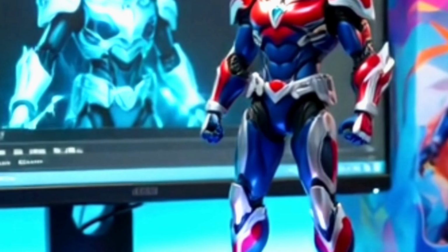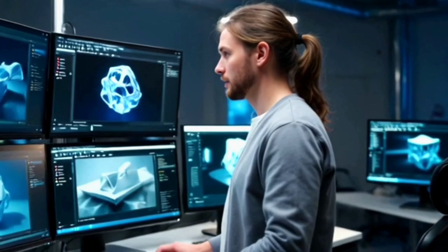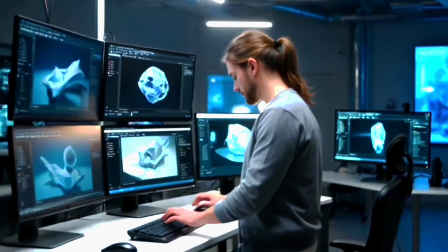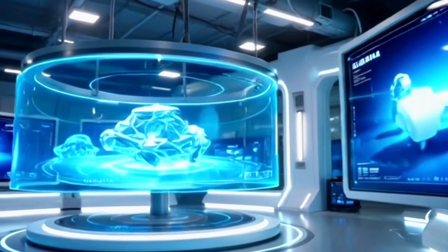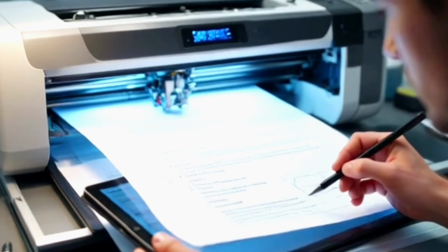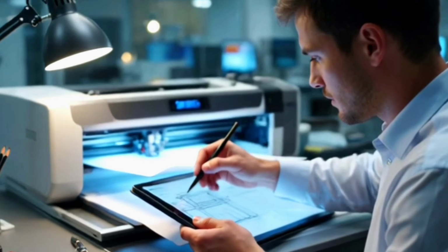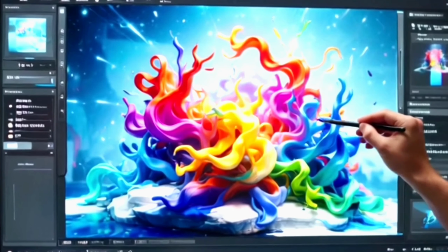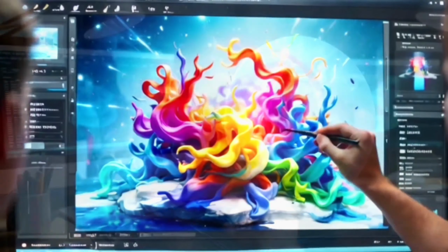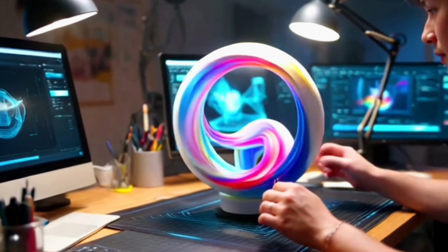Rule 2: maintain a consistent 45-degree angle. If you change the angle midway, it suggests a different part or material. The rib exception. This is a professional secret. In many standards, thin features like ribs or webs are not hatched, even if the cutting plane passes through them. This prevents the drawing from looking too heavy and misrepresenting the part's strength.